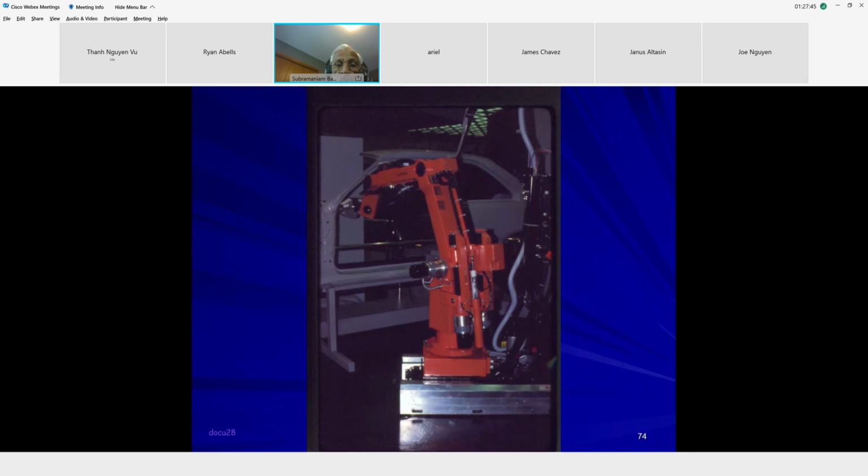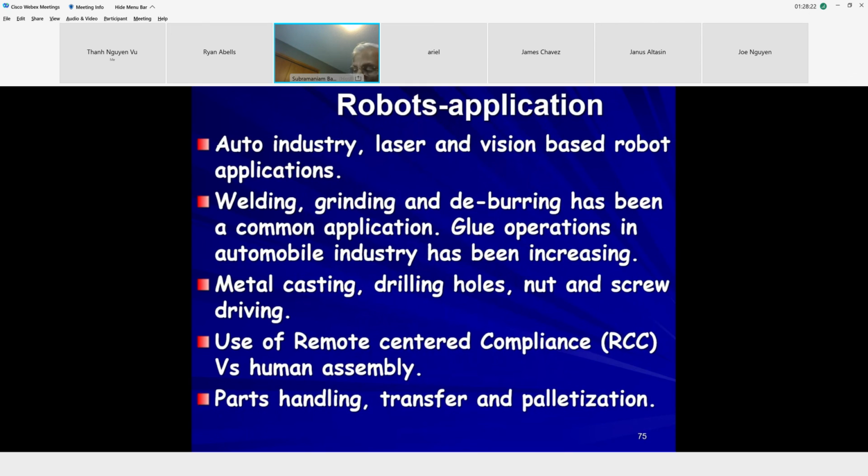Okay, so in the case of spot welding, right here, that's the car body. The robot is on a 7th degree of freedom. It can go along the entire length of the car. It'll do the spot welding here, spot welding here, spot welding here, whatever. There is no path control that is needed except point-to-point application. But what is used here is a 5-axis. I have this machine in my lab, a 5-axis robot made by ABB, ASEA Brown Boveri.